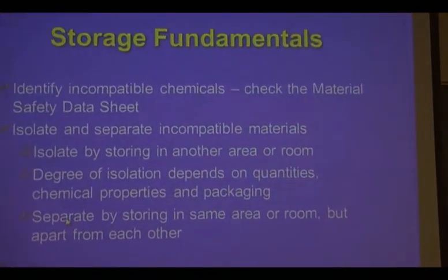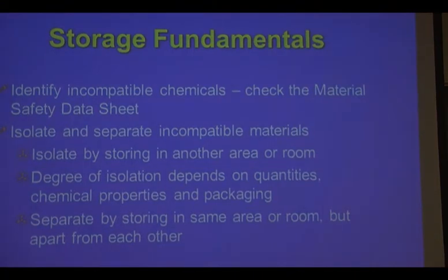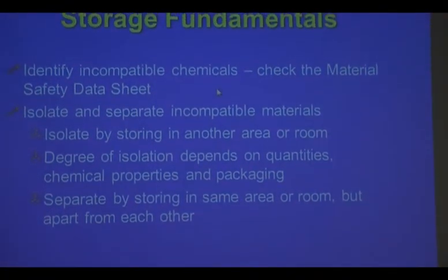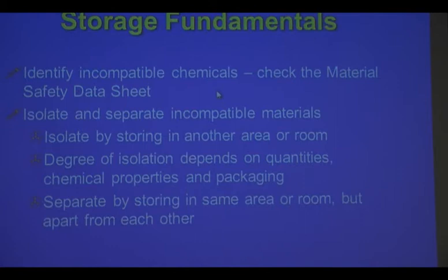Okay, storage fundamentals. This is storing stuff in your area. Make sure that things are compatible. Don't store water next to sulfur, or potassium, or that kind of stuff. Isolate and separate incompatible materials by storing them in another area, having enough insulation between them, not temperature insulation, but things that will keep them from reacting.